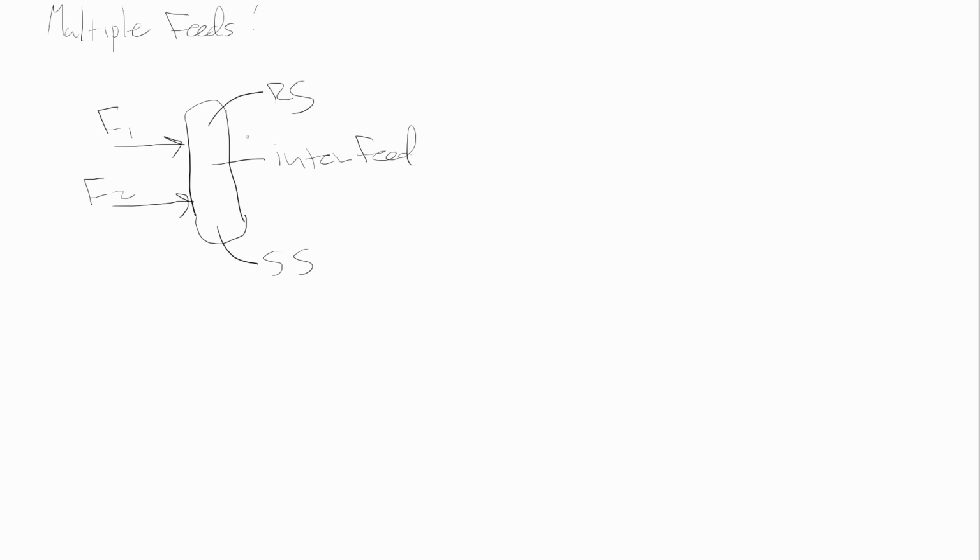And of course, what defines a section is a change in liquid and vapor flow rates, which corresponds to a change in the slope of the operating line for that section. The slope of the operating line is simply going to be V over L for a given section. And just as a single feed changed V and L between the rectifying section and the stripping section for a single feed column, now with 2 feeds we have a third V over L, a third operating line slope.